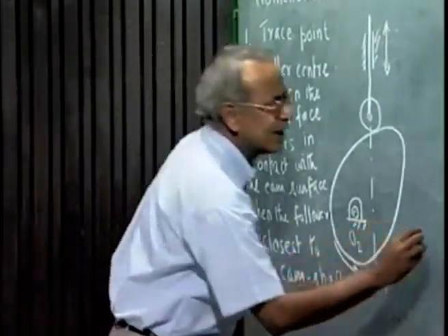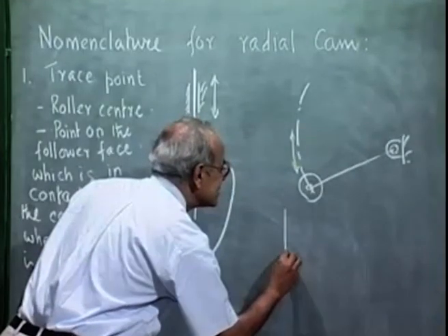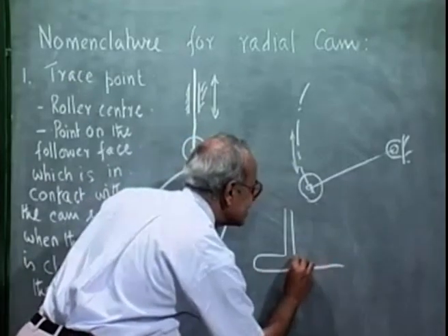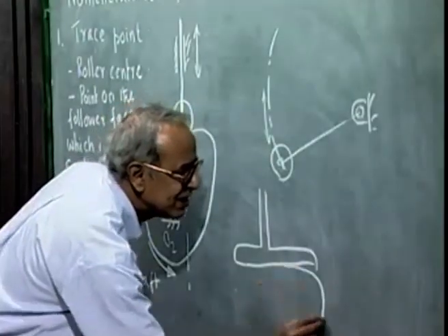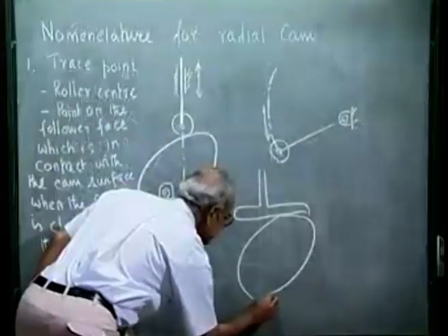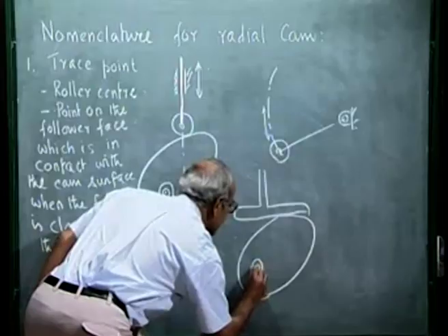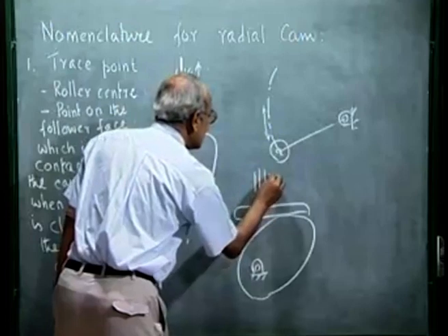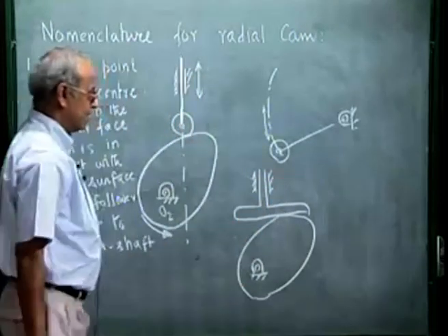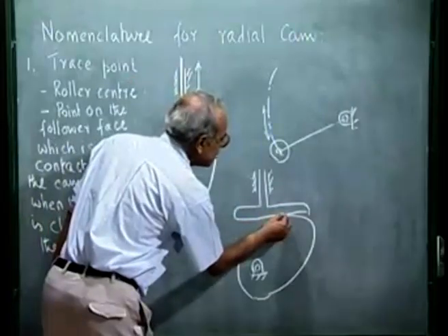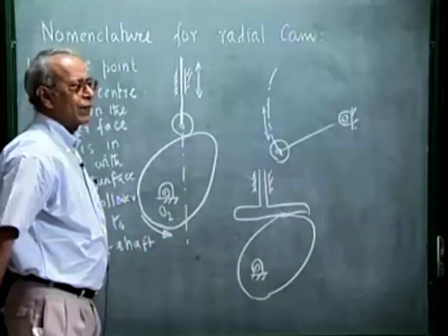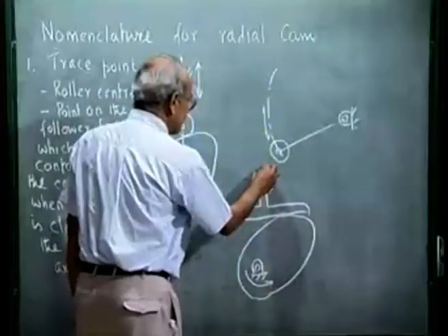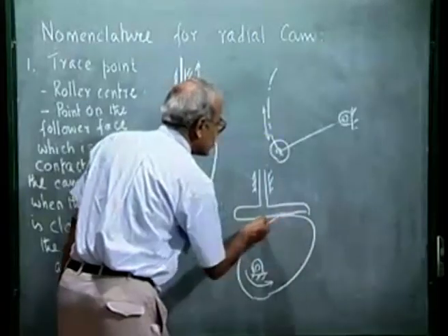As we see in the case of a flat face follower, at this instant, it is this particular point of the follower face that is in contact with the cam surface. But as the cam rotates and the follower moves up and down, this point of contact shifts on the follower face.